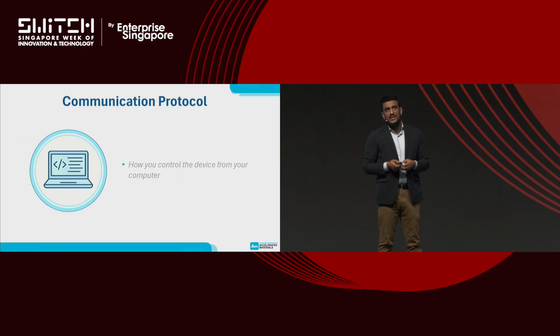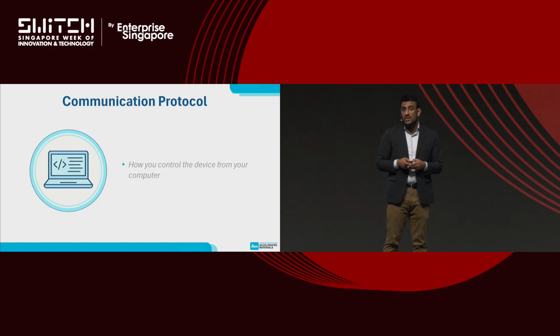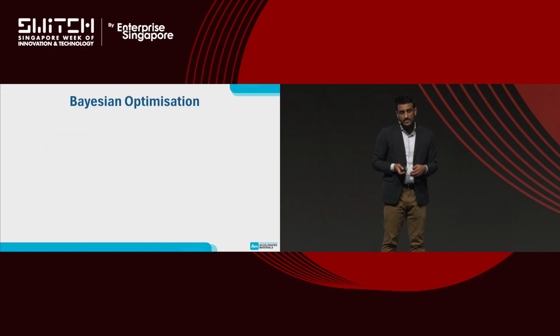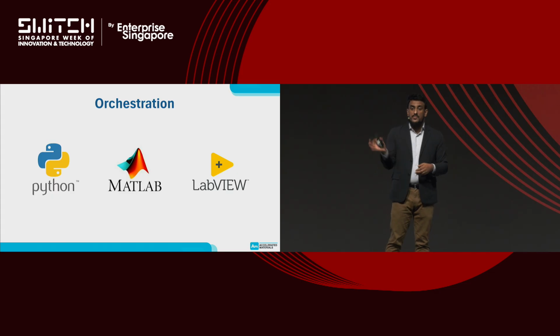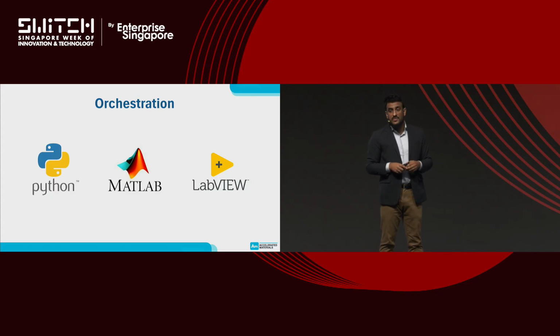I took the slides out here, but my advice is, if you've got serial communication, go with that first. It's super easy. The next one is Modbus. It's basically like serial, but your commands are standardized. And then the last one I can mention is OPC UA. It's a new open communication protocol. Most of the device manufacturers are following it, and it's really easy to implement with all of the technologies that I'm going to mention on the next slide. So I've mentioned 3 communication protocols, and then you can decide how you want to implement it. The list is by no means exhaustive, but it provides a good place for you to get started.